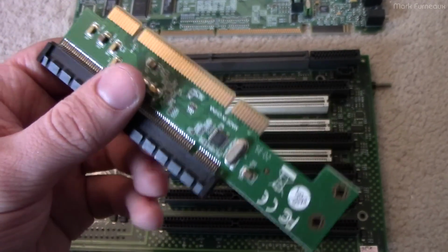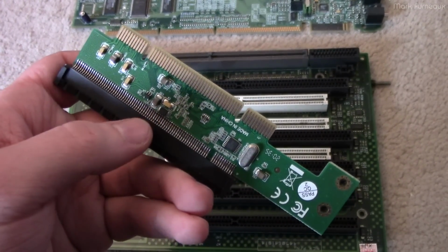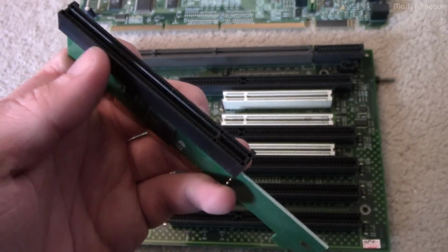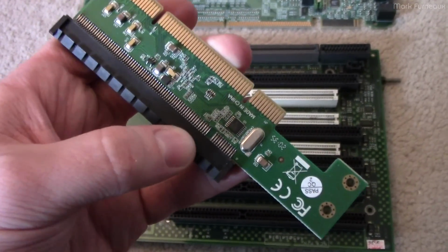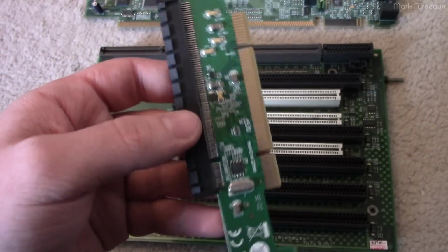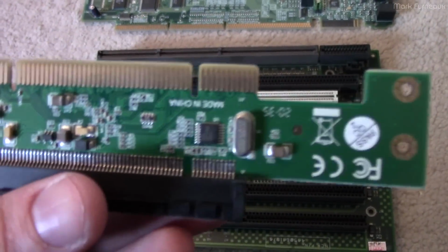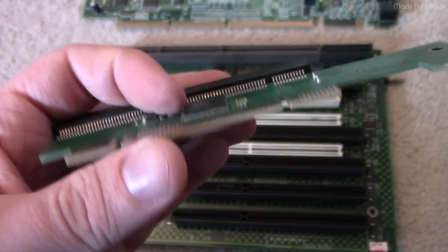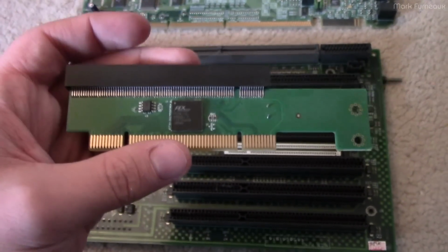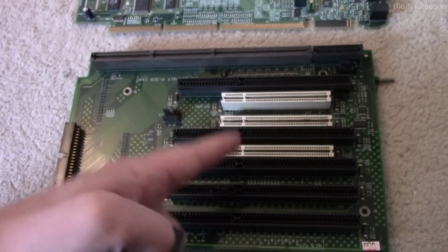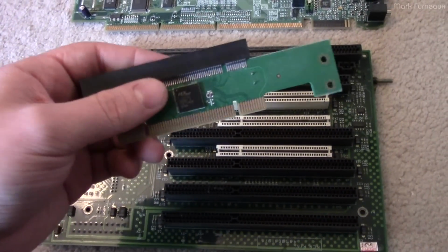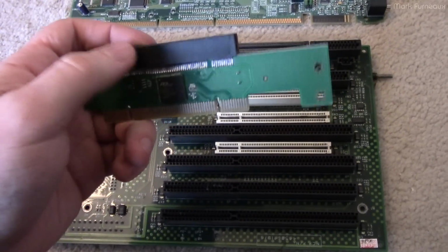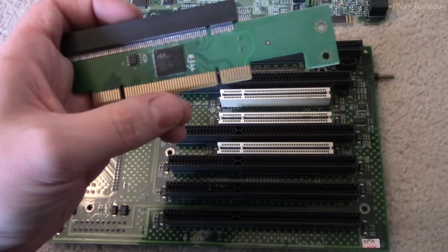And this is a simple riser. You can see it's just a regular 32-bit PCI slot, and then we have an X16 PCI Express slot. Now, obviously, it's not electrically X16. It's actually electrically only X1, but it's got a full slot here just for mechanical rigidity. On this side, we really don't have anything special, basically just an oscillator, some sort of management and power supply, and then on the other side, we just have the bridge chip, and that's it. So even though this board was designed before PCI Express, it's the PCI Express side which has the backwards compatibility to work through PCI.